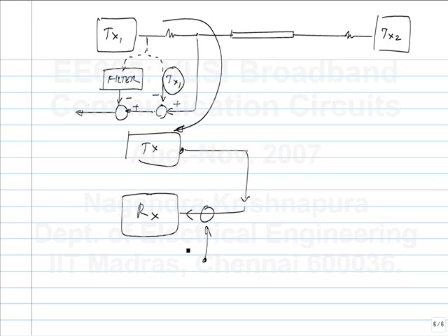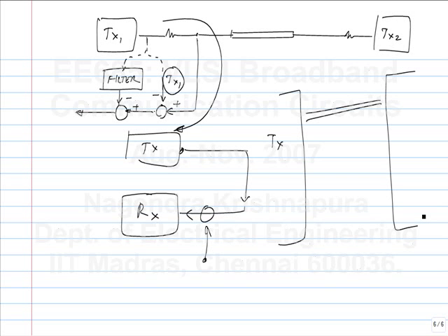Oh, yeah. I mean, if you have that, then you will have an even bigger echo problem. But typically, when I said multiple transmitters, I assumed separate transmission lines for each case. So potentially you can do that also. You can just dump all the data onto a single line. In which case, we are talking about near end crosstalk. This is like an extreme case of crosstalk, right? You have connected the two lines together. So this is an extreme case of near end crosstalk, and you will have to cancel all that out also. But typically, you will have different lines at higher speeds.